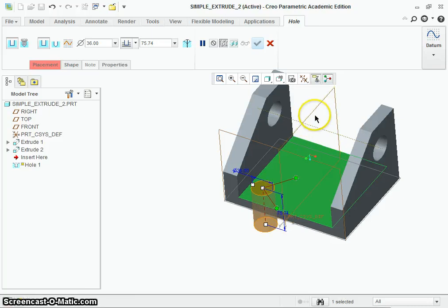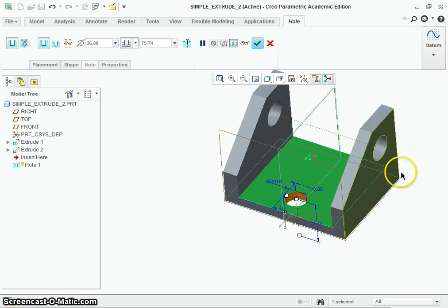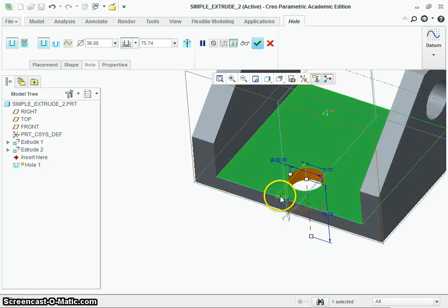Like I said before, we did this so it was symmetric about this right plane. That's what our extrude on both sides option did. So what we're going to do is drag one down to the front so we can get that depth, and then we can also add it to that there. If we want it to be coincident, just put in a 0 distance there, and for this depth we can say maybe we want it at 35.